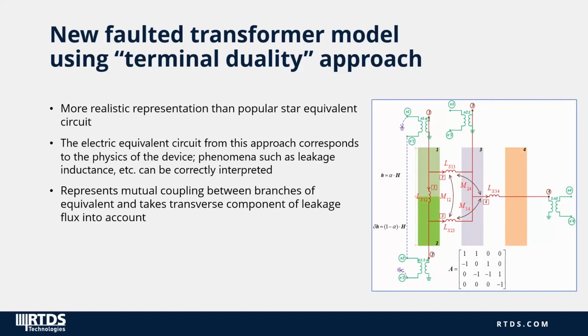New transformer models have been developed based on the terminal duality approach. The new models provide a more realistic representation of internal faults than can be provided using the popular star equivalent circuit. The terminal duality approach also allows for mutual coupling between the branches of the equivalent circuit and the transverse component of the leakage flux to be taken into account.